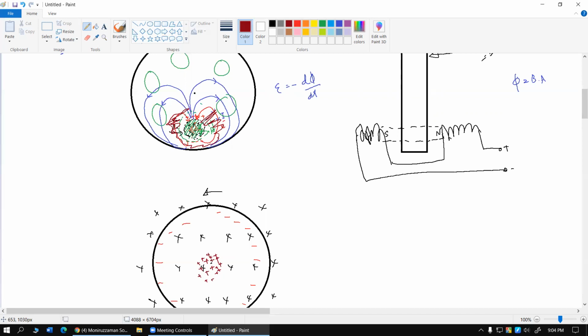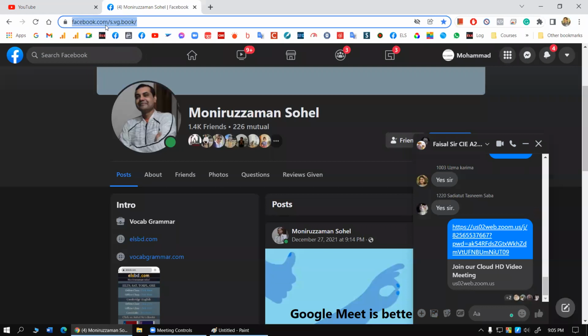Affecting the whole disk with magnetic field will give rise to an EMF, but that will not give us a continuous current. We need certain locations to produce the EMF, and certain other locations should act as the conductor, unaffected by the magnetic field, providing a return path for the current to flow by. So the definition of eddy current can be given in this way. Let me just give you a very basic definition.